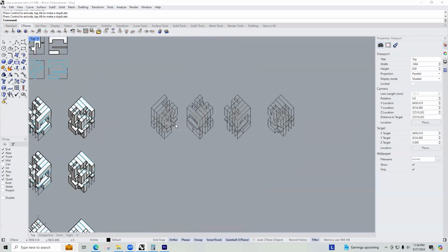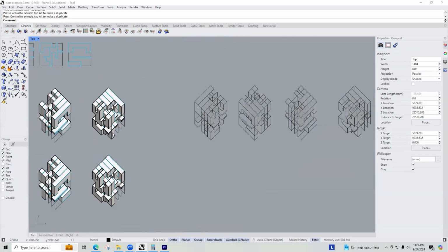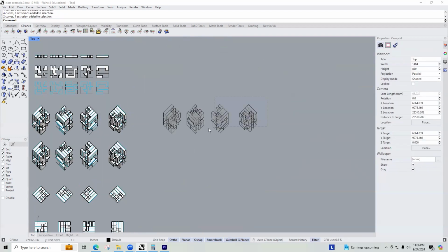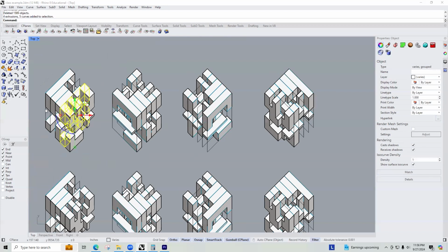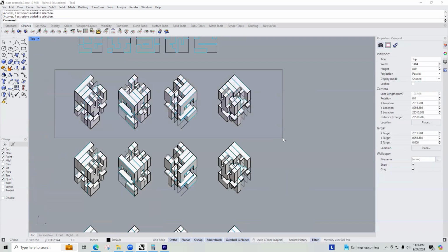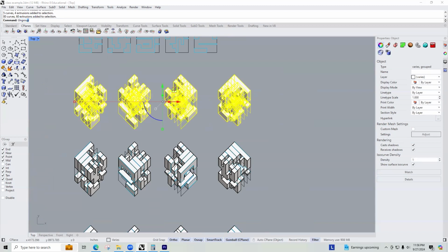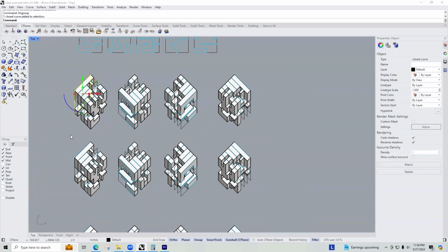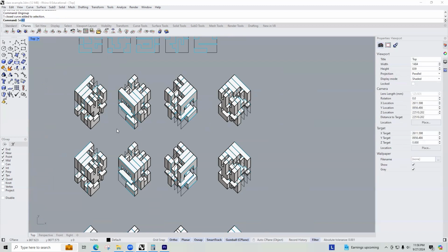All right, it would probably be better to not have these vertical lines in your Make 2D. So feel free to just delete that and do this again without those lines. So I'm just going to ungroup these. All right. And then select curve.